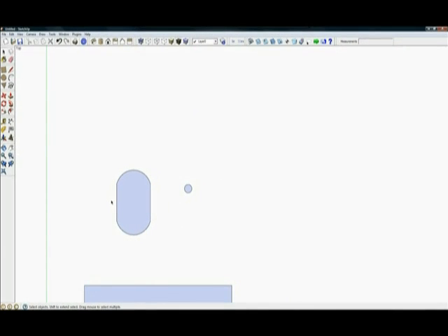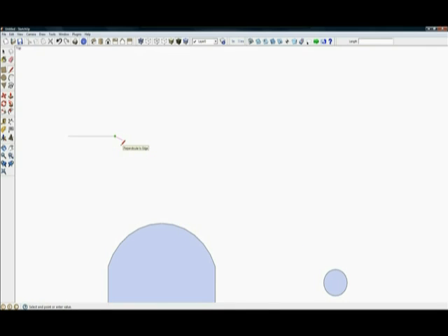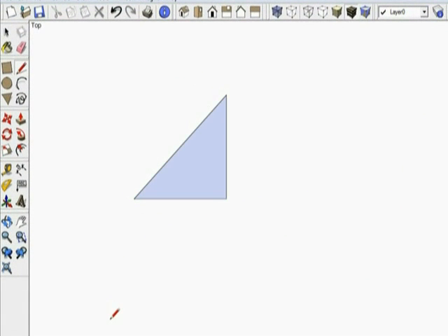And the fact that we can work with squares, we can work with rectangles, we can set the scale to be any line length that we want, like I showed you by taking your tool, click once, draw, maybe say 2 for 2 inches, hit enter. Now we've got a 2-inch line. If I wanted to make another 2-inch line, I just stretch it up. I don't click. I hit 2 and enter. Now I've got the basics of how I can start making a 2-inch square or an isosceles triangle, either way.